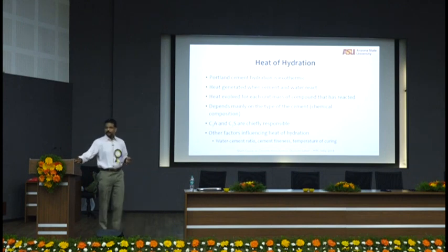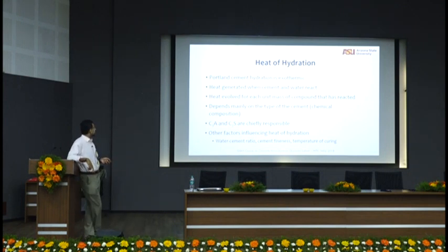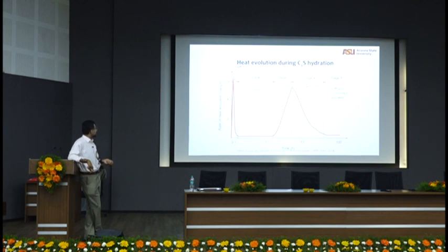Exothermic reaction, all of you know that. Portland cement is exothermic. Heat is generated. C3A and C3S are chiefly responsible. This picture, all of you have seen this? All very familiar. Initial dissolution heat. Heat goes down. You have a plateau where CH nucleates. This plateau helps ready mix manufacturers to carry the concrete around to wherever they want without further reactions. You can add chemical admixtures to extend this plateau. You can add retarders to extend this plateau. You can add accelerators to shorten this plateau.